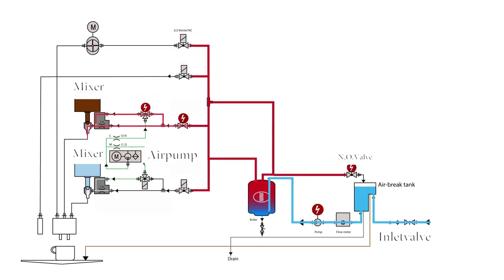Water flows through an opened two-way valve to the water restriction receptor. Inside the water restriction receptor, the water channel narrows. As a result, the speed of the passing water increases, lowering the air pressure at this spot. The lower pressure draws in air through a separate air channel connected to the three-way valve. This is the so-called Venturi effect. The resulting pressurized water jet is required to achieve the desired mixing performance.